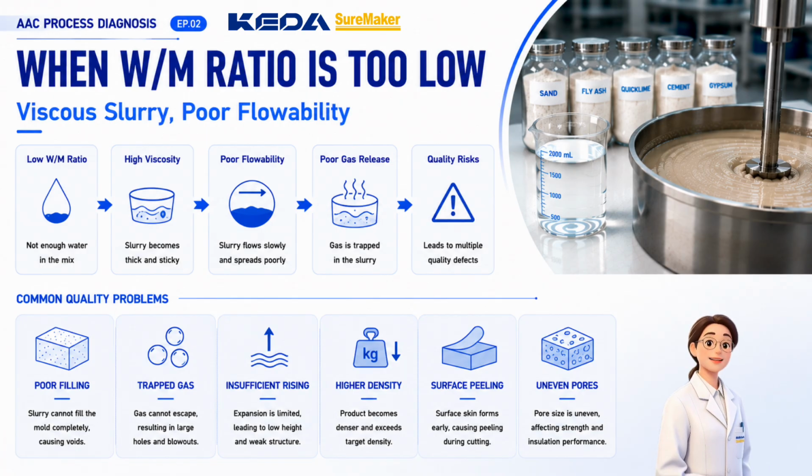In other words, when the water-to-material ratio is too low, the problem is not that the slurry is too thin and cannot stand. The problem is that the slurry is too viscous. Gas cannot expand properly, and the slurry cannot spread evenly.